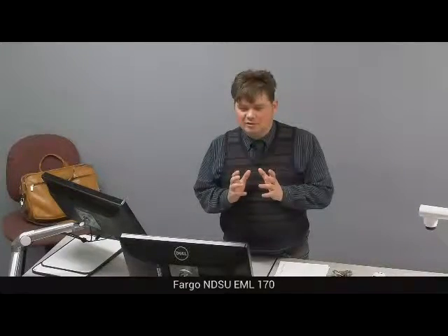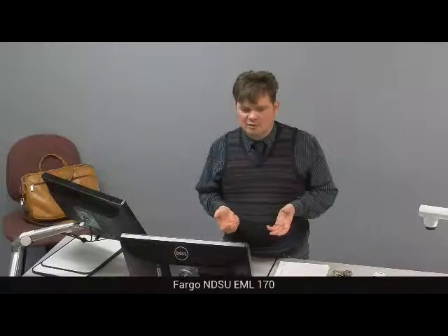Okay, I just want to say, I didn't mention this because we hadn't had a chance to talk, but the density is a little high. The density reported for epoxy in that kind of setup would be around 1.2, and I calculated 1.6. So maybe too much pressure was applied to it, and when it is too much compressed, it may come to compression-induced degradation. So something may be wrong.